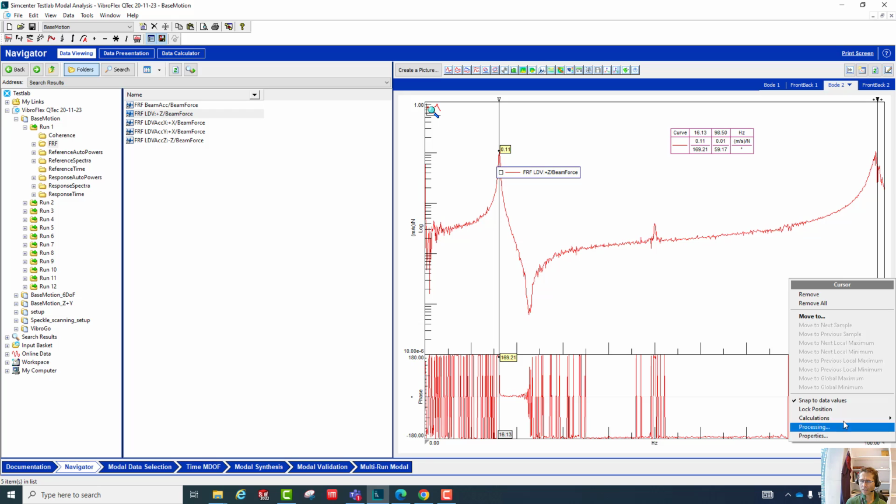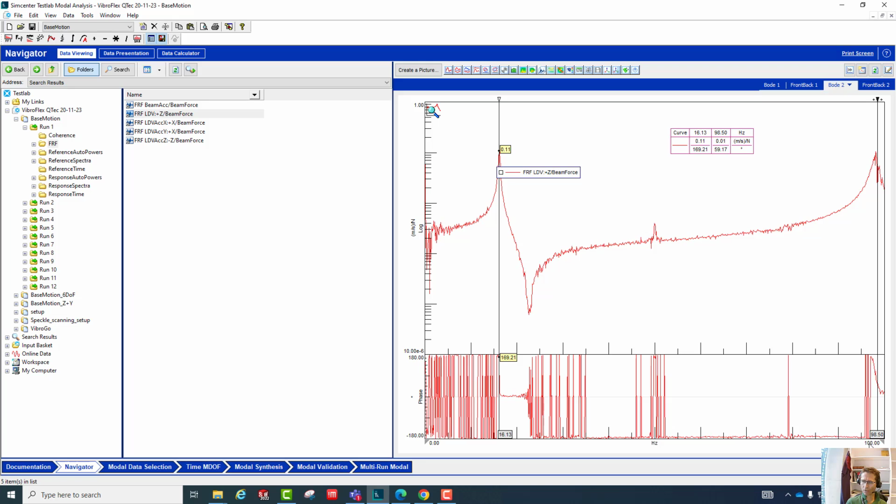If I right click on here, there are various other options, and depending upon exactly how I click, whether left click, right click or double click, I get different options. Here you can see the limits for the axis. Currently they're fixed. They were free, determining the limits based on the data that was displayed in this preview mode window. So by double clicking and specifying this upper limit, I've effectively changed the limits to fixed.